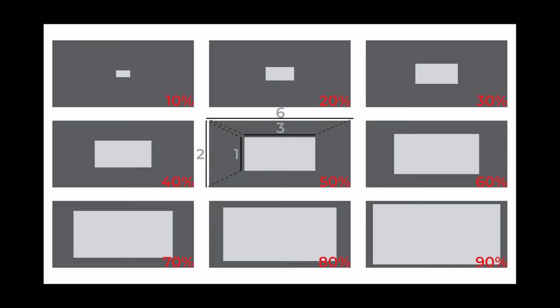The ratio is all about thermal comfort and energy usage, implying that the two factors are coherent in many ways. The ratio is extremely simple. It is the proportion and orientation of exterior wall surface area that is glazed. In other words, the net glazing area divided by the gross wall area.